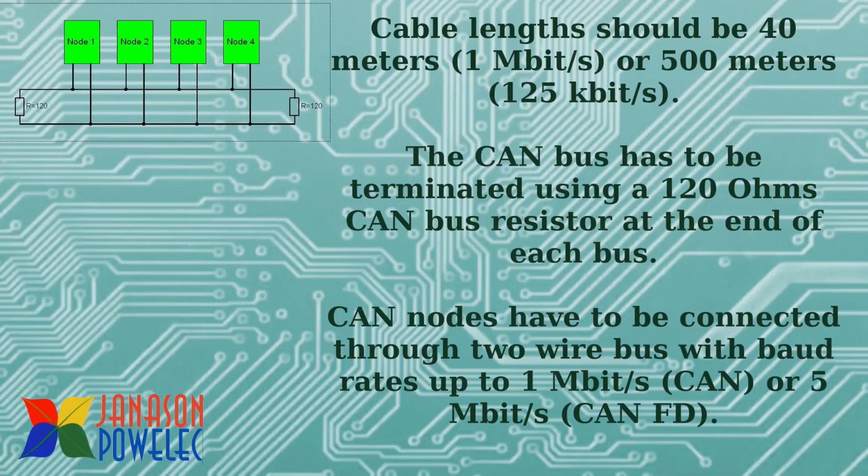ECU or not. The information about who the message belongs to is embedded in the data itself. There is a particular field where this information is saved, that identifier. That identifier is decoded to understand whether that particular message is for that ECU or not. This is where the communication happens.